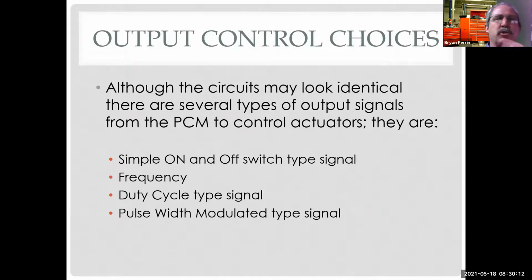But being able to measure current, I'm just not buying that. To control current flow and protect the module better, that I would buy, because now I'm controlling the ground, I'm controlling the complete circuit. So even if there's a short, I can't flow too much through the circuit because I'm controlling how much current I'm putting on the circuit. That I completely buy, and I think that's why they're doing it, because it's a lot more expensive to do.